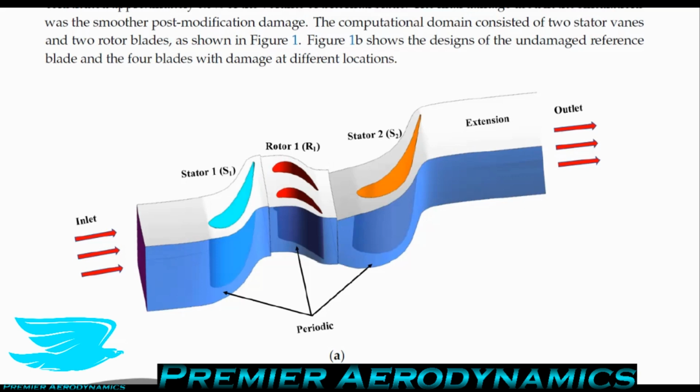And the reason why you have a stator compared to a rotor is that the rotor moves and it takes energy out of the flow. But by doing that, the flow then will change direction. And as the flow goes downstream, you want it to be aligned in a certain way. So the stator behind the rotor aligns the flow so that you can use it more efficiently. So you understand, first of all, what the flow is going to be traveling like, and secondly, directing it to where you want it to go. And often you'll have a stator upstream as well to direct the flow into the rotor in a particular way, so to increase the efficiency of the rotor itself. So you have a stator upstream, then the rotor, then a stator downstream.